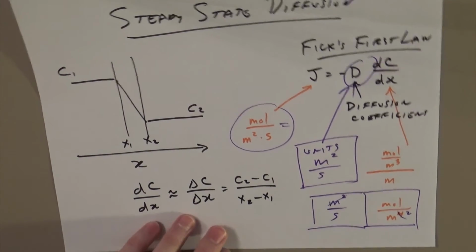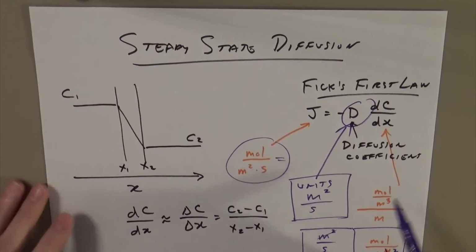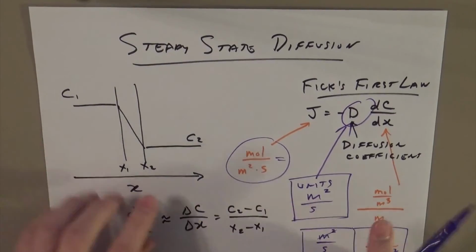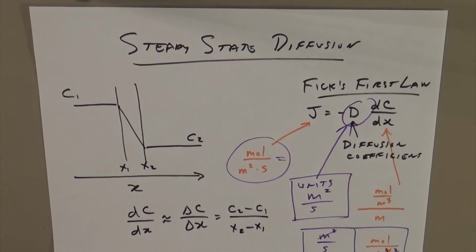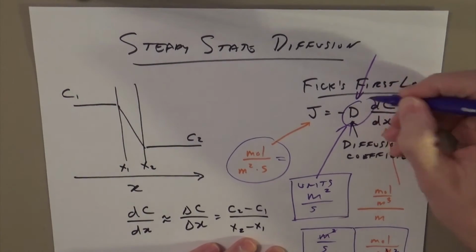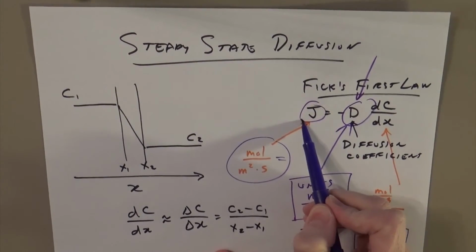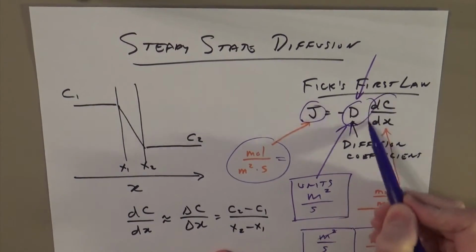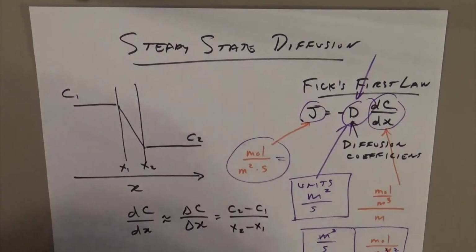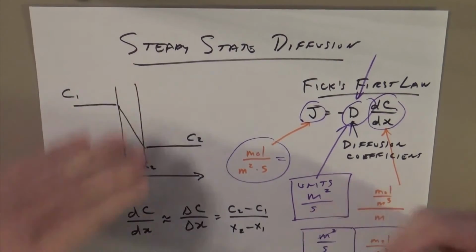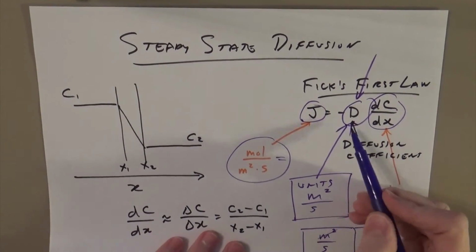The diffusion coefficient then gives us a relationship between the rates. This is also where the material science comes in, right? Because this is just a measurement of how much stuff passes, and this is a measurement of the geometry, the amount here and here, and this is where the material science is, and that also means that is where the interesting properties come from, and in this case, it's going to be the temperature dependence.